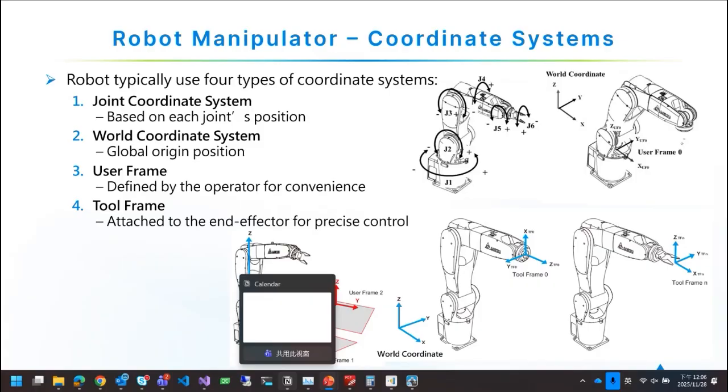I am a robot, and if I want to define a user frame here, what we can do is set a command to the robot and go to this user frame 0, so we can export the points by this user frame, so that when we modify the position of this product, we don't have to reprogram again, because the frame will give us the info about the position between the frame and the robot.